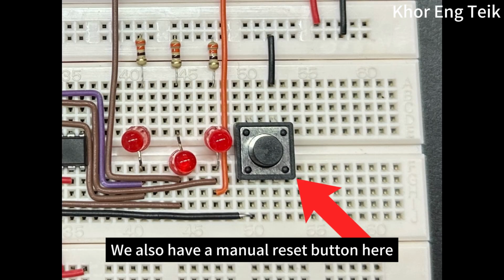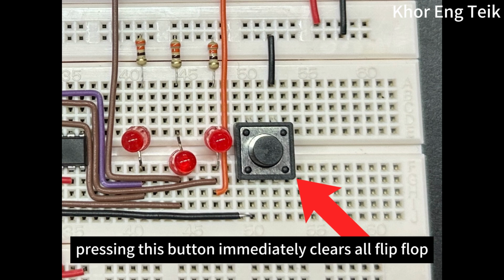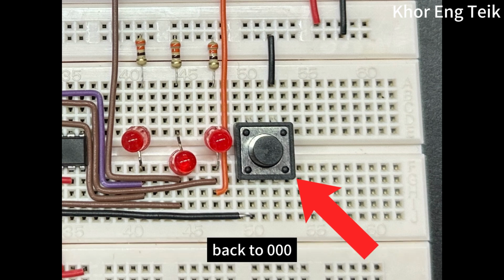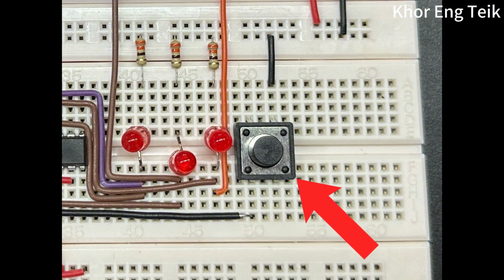We also have a manual reset button here. No matter which state the circuit is currently in, pressing this button immediately clears all flip-flops back to 000 and the display returns to 1.